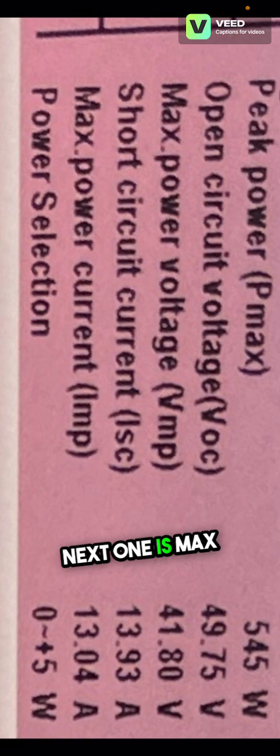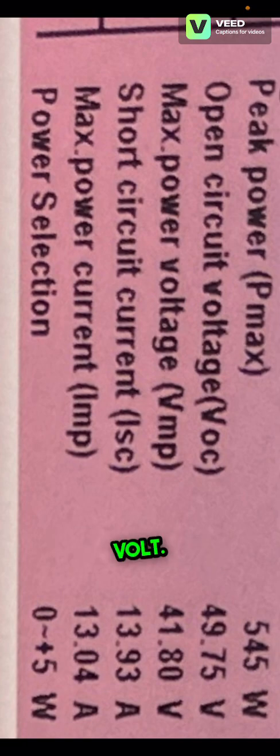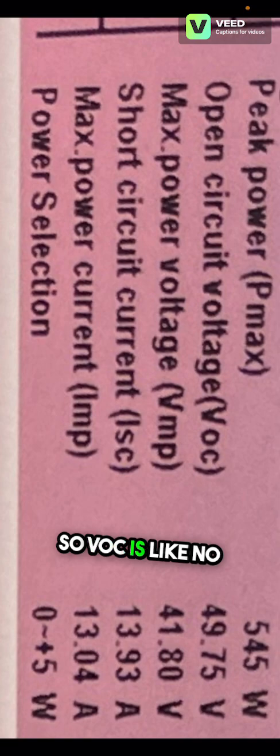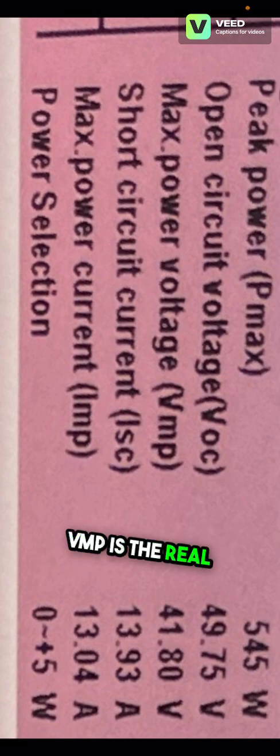Next one is maximum power voltage, VMP, 41.8 volts. This is actually the working voltage. This is the actual voltage when the panel is properly connected and producing full power. So VOC is like no load voltage, and VMP is the real working voltage.